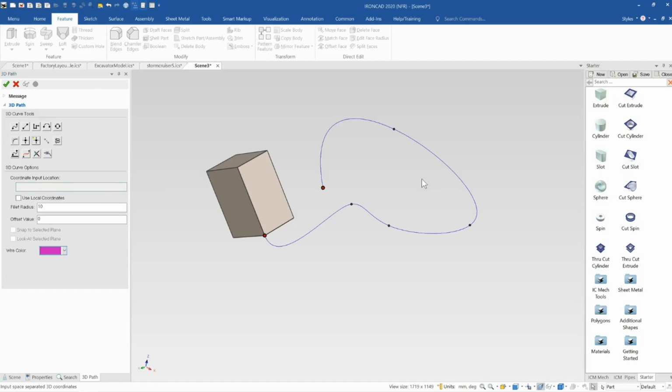So a good thing to do is to click into empty space and then click on that point again and activate the tri-ball. As long as it doesn't think you're trying to type, it'll activate the tri-ball on the point, which is what you want. If you click in there and you're clicking on this and it's typing Q and the tri-ball's not coming up, then you just click into empty space, click on the point, and you've now got the tri-ball to control that.